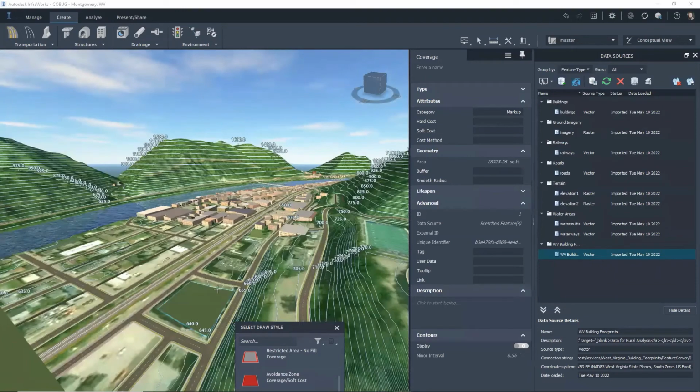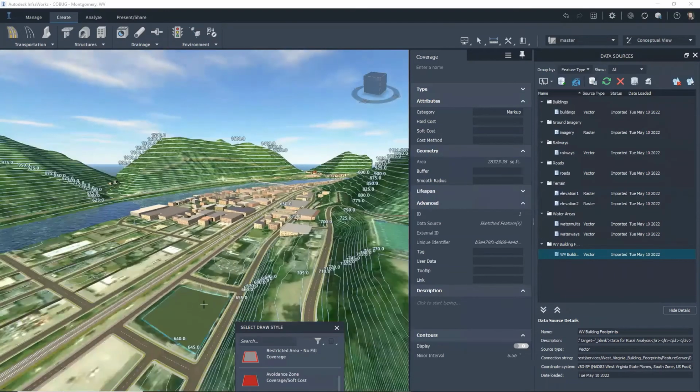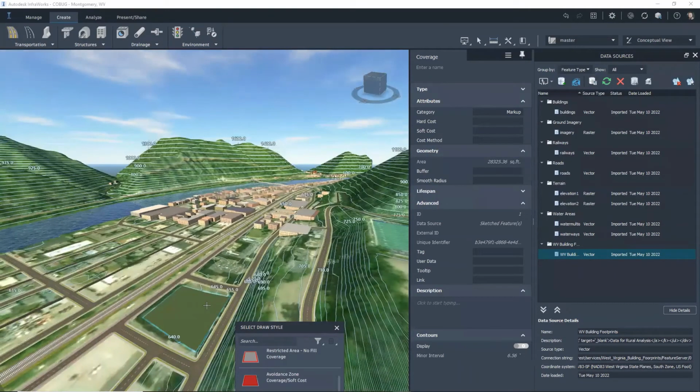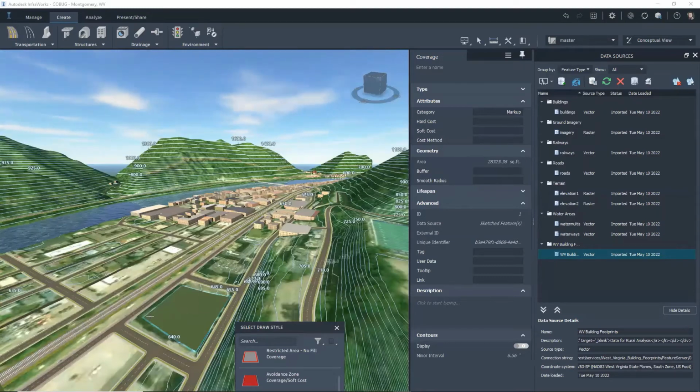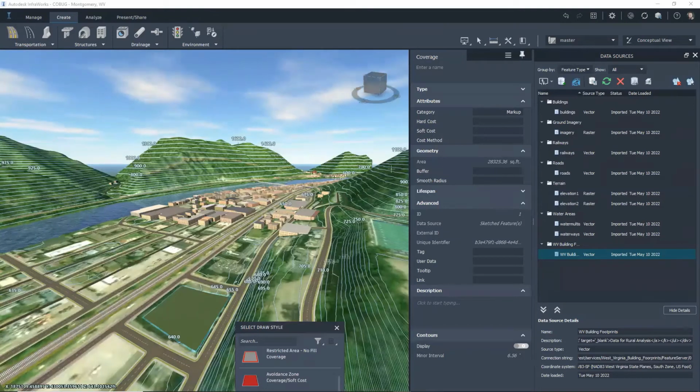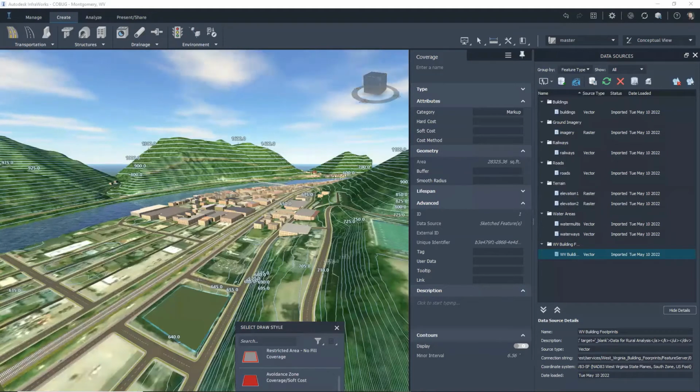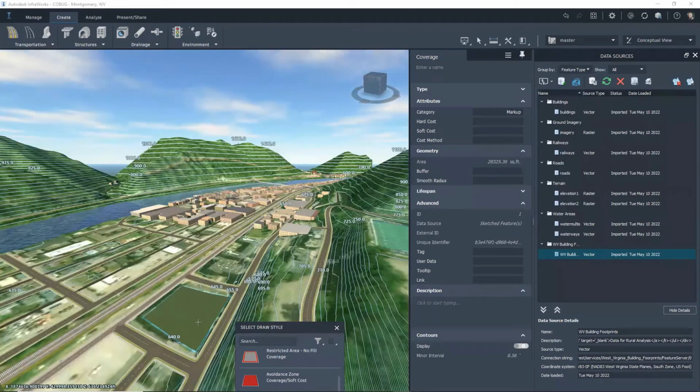So something else to keep in mind is that OpenStreetMap data is generally not super accurate. They're pretty big coverage areas, like 30-meter resolution. And so if you spent time creating a topo surface model of your site that your civil engineer provides, there often can be some slight differences between what this is generating from photogrammetry and LiDAR scans, essentially, between your building and what's available on site.